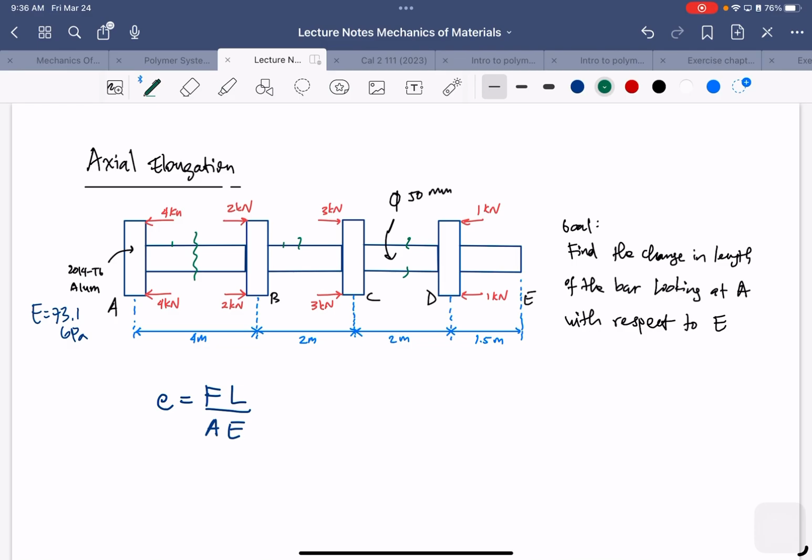If you want, we could cut each of the members and see what is going on inside the member. If we take from A and cut here, we have 4 to the left, which means we have a total of 8, so we need a resultant of 8 going there. So in this member, let's say we have the force here, 8.